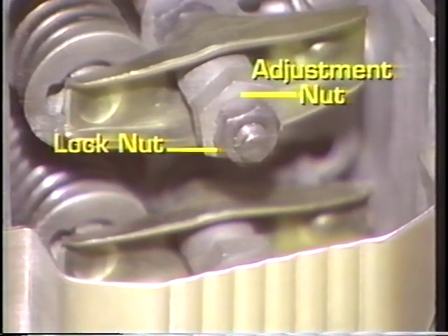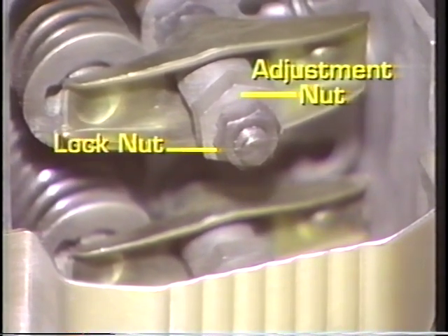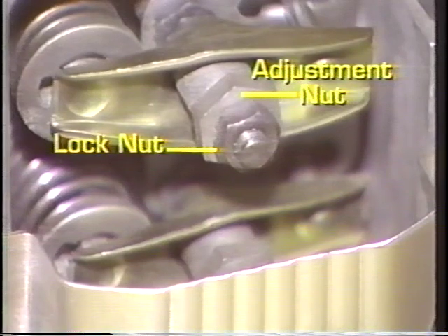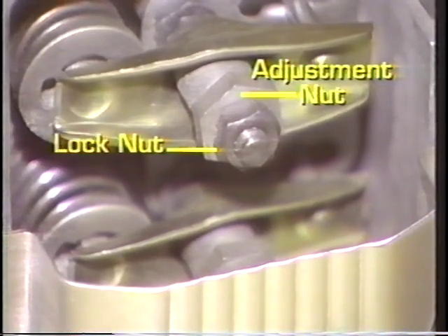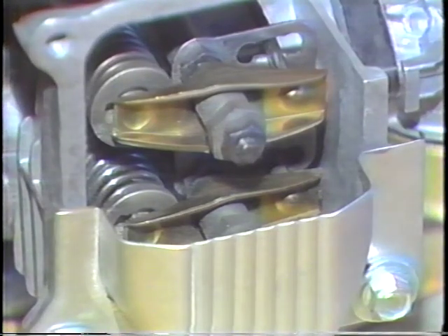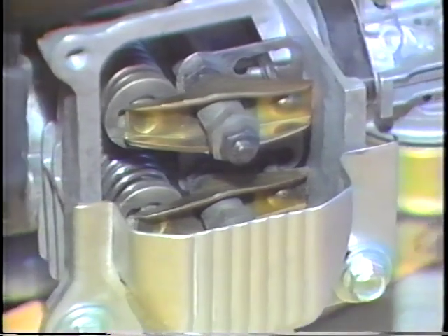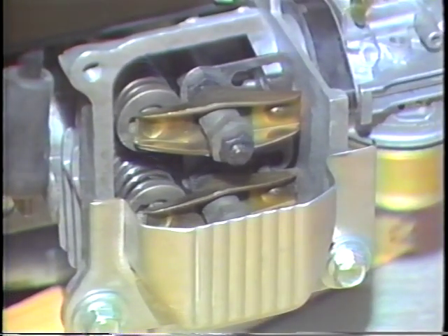To keep oil spray in the engine, a valve or rocker cover and gasket bolt over the top of the head with an overhead valve design. The valve cover at the bottom of the picture is usually made of lightweight stamped steel. A gear on the crankshaft drives a larger gear on the camshaft to turn the cam at 1/2 crankshaft speed. Helical cut crank and cam gears are sometimes used for quiet operation.